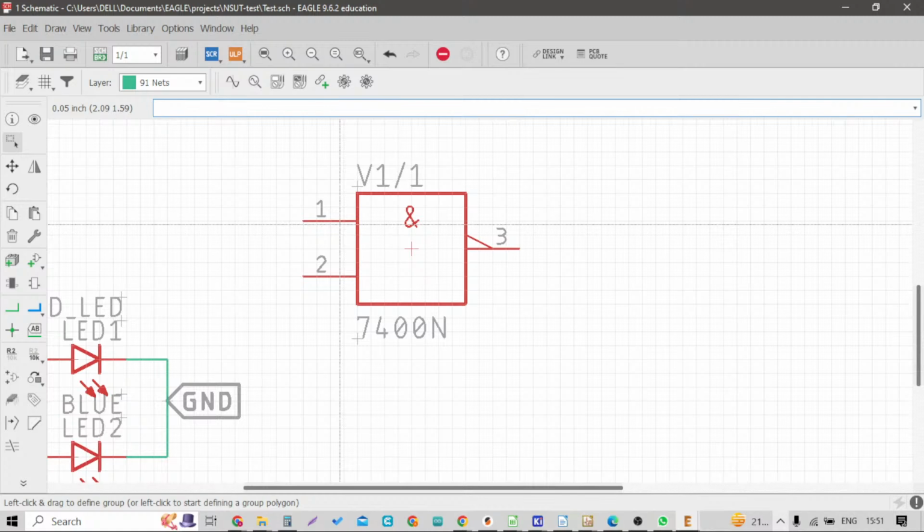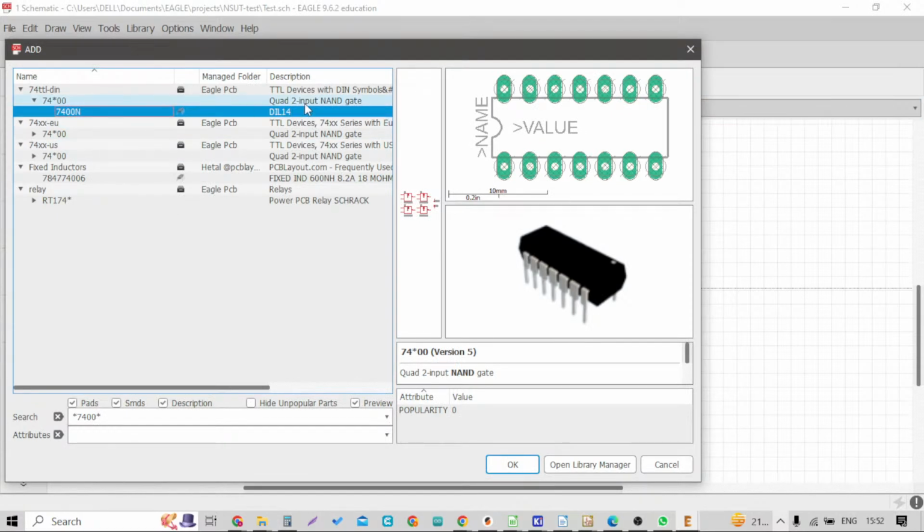To get the rest of the parts of the given IC, I can use the invoke tool. So the invoke tool basically helps us in showing all the sub parts of a given package. So in EAGLE, mostly what happens is if there is an IC where the features are replicated in the same IC, let's say this IC that we have, 7400, is actually a NAND gate IC, and it is a quad NAND gate IC, which means that there are 4 NAND gates in this IC.